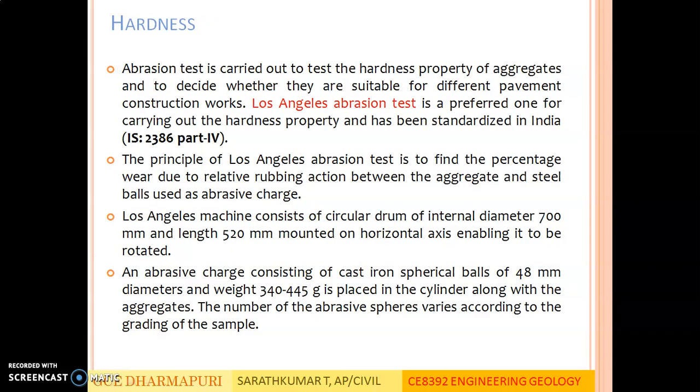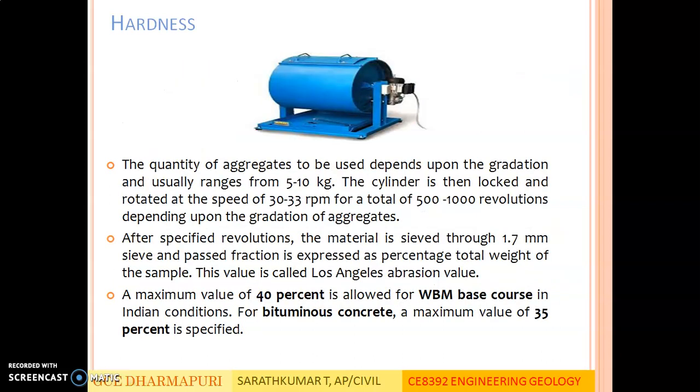Hardness. It is very similar to the abrasion resistance test. Instead of rotating the drum with only the aggregate, here we are putting steel balls inside it to find out how hard the rocks are. The Los Angeles abrasion testing machine is shown in the figure.